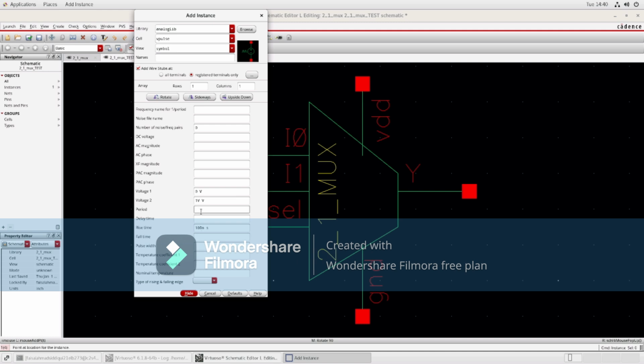Period, first let's make period 10 nano, then pulse width should be 5 nano, and rise time should be 0.1 nano, I think.